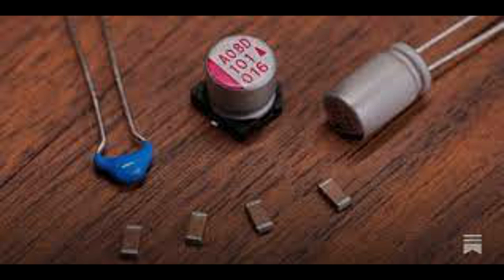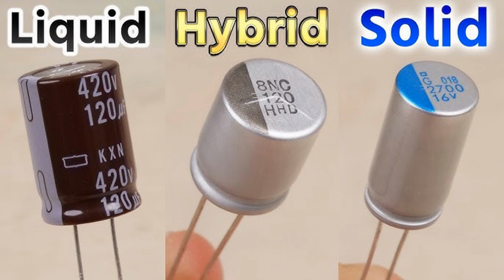Decoupling capacitors act as a filter by providing a low impedance path to ground for high-frequency noise and transient signals. This helps maintain a stable DC voltage for the circuit. Application: decoupling capacitors are placed close to power pins of integrated circuits, ICs, to reduce noise and stabilize the voltage supply. Applications: power supply filtering.